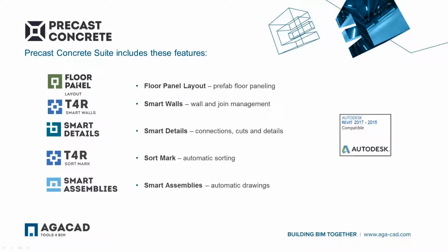We have Floor Panel to create precast floors, then Smart Walls to split walls into panels, then Smart Details. I will talk about these 3 today. Smart Details handles connections, cuts, and details. Then Sort Mark to automatically sort, and Smart Assemblies to create drawings.